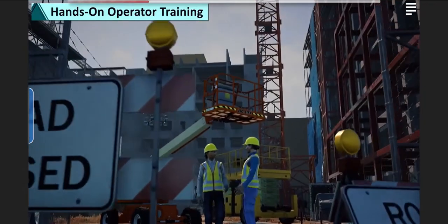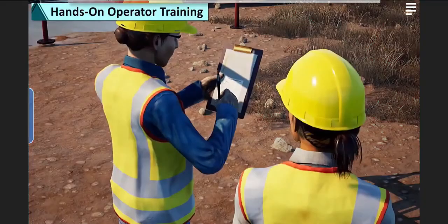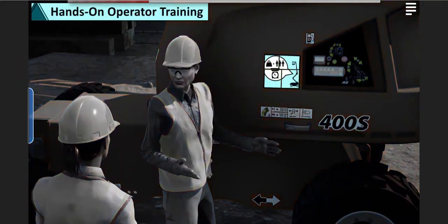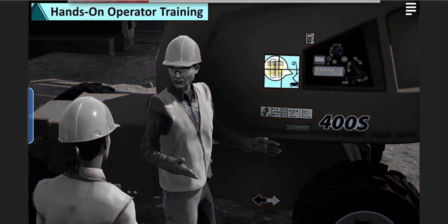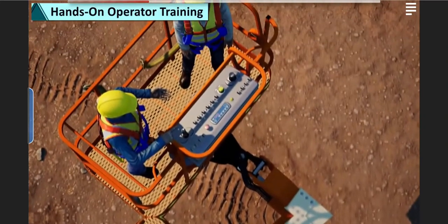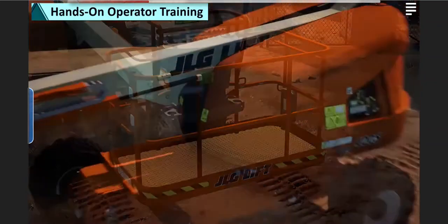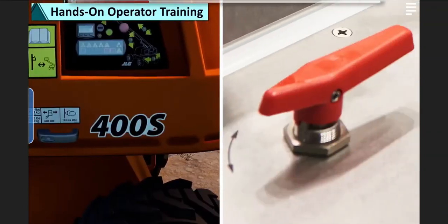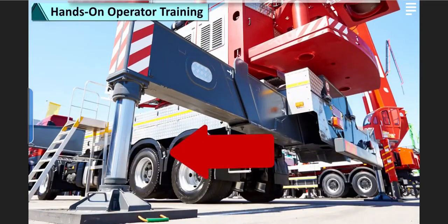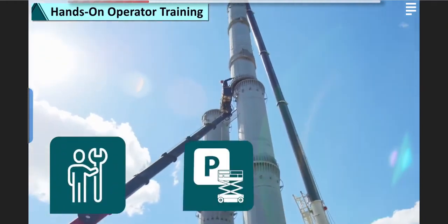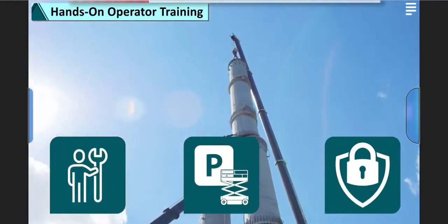Next, the trainee must demonstrate understanding of features, operating characteristics and limitations of the specific model of MEWP, including maximum intended load, load capacity, and reach capacity. They must also demonstrate understanding of the purpose and function of the MEWP components, controls, and devices, including platform, ground, and emergency descent controls, as well as stabilizing devices such as outriggers and extendable axles. Finally, they must be able to demonstrate proper operation of the MEWP, including proper setup, parking, and securement procedures.